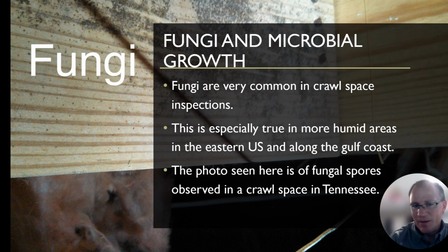There's a lot that could be said about these things, and each state has a different idea of how they look at this as far as treatments, as far as what you need to write down on inspections. But I did want to let you know that fungi are common in crawl space inspections. This is especially true in more humid areas in the eastern U.S. and along the Gulf Coast and even in the Pacific Northwest. So if you're in a drier area, say like West Texas or Arizona, California, Nevada, you may not see as much of this because the relative humidity is so much lower.